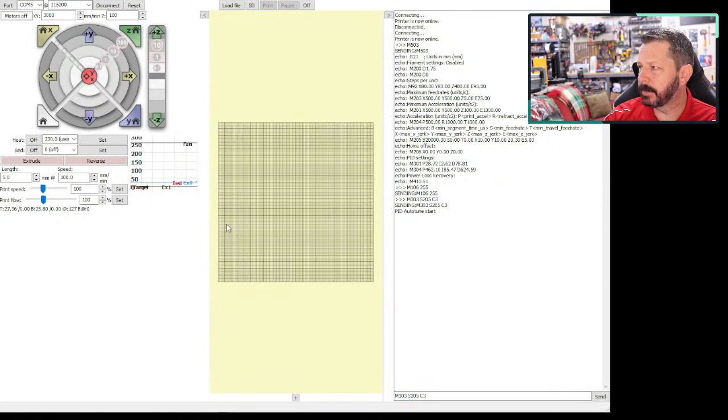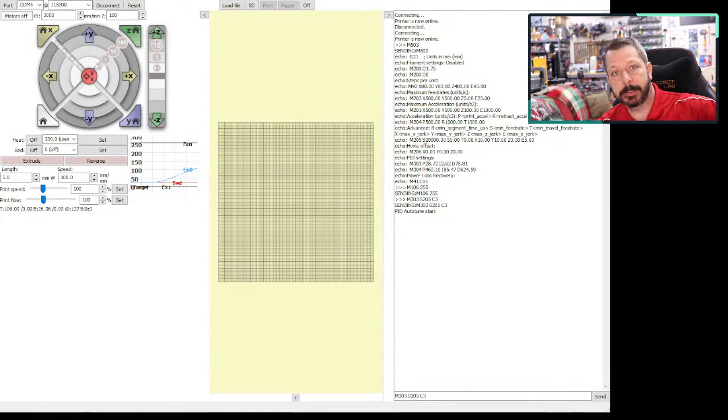You'll notice over here in our little window, you can click on this if you have Pronterface actually open, and the window will get bigger. It just won't show up on your screen since it's a new window. But you can see the E0 or EX0 line is starting to creep up. It's going to go to 200, probably a little above 200, then turn off, on, off 3 times. And then we'll get some new values for P, I, and D in our printer, and we can assign those. That won't actually put the values in the printer. It will just tell you what they could be based on the algorithm and your current setup.